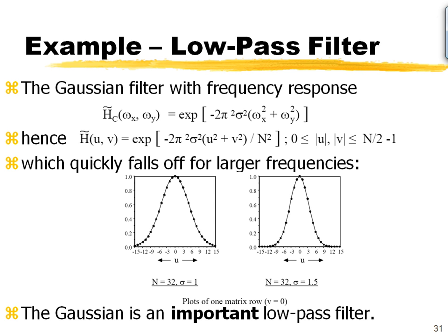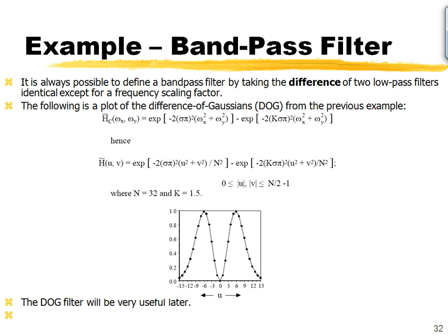So this becomes a great low pass filter, because basically it's retaining all the low frequencies. The amount of low frequencies we retain is simply dependent on sigma. Okay. Now a band pass filter basically is something that removes high frequencies and low frequencies, right? So a typical band pass would look something like this: 0 coefficient, or 0 weightage, around frequencies that are 0, and of course 0 weightage around frequencies that are high. Everything in between we want to retain.